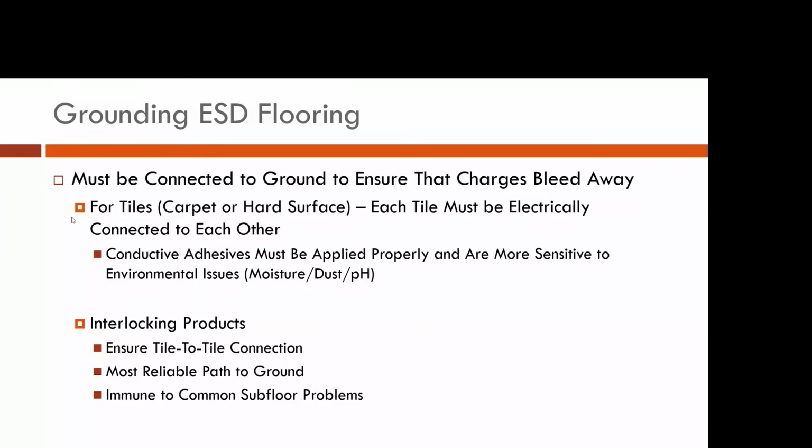You've got to be cautious of interlocking systems that require underlayments or adhesives to help create the conductive plane, or put down copper grid systems. Failures in those can be very tricky to pinpoint.